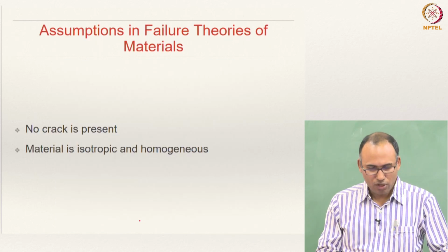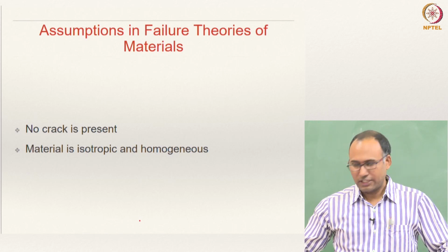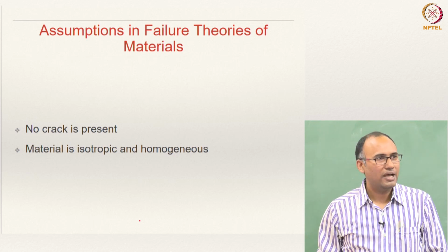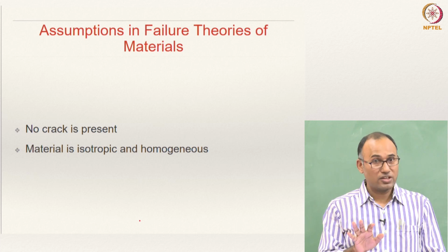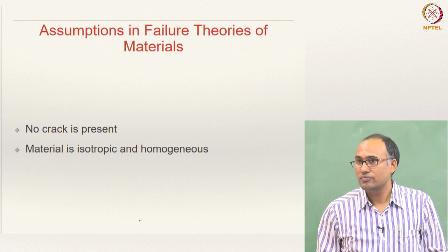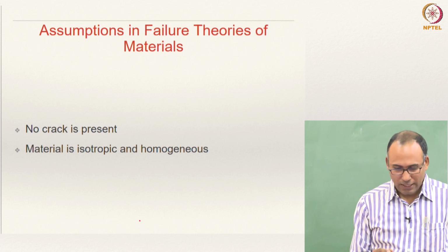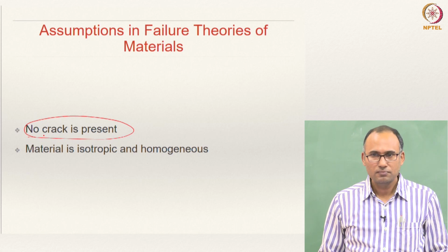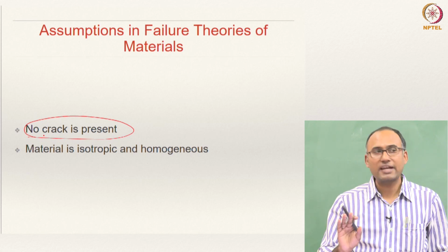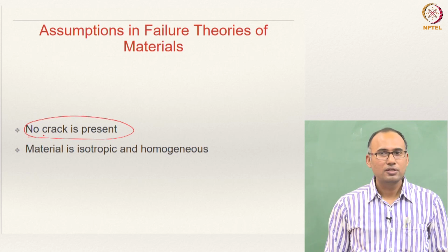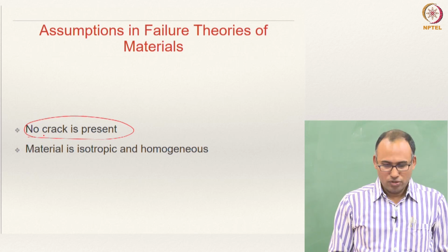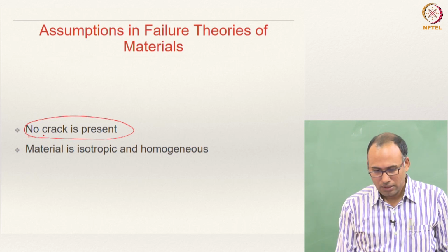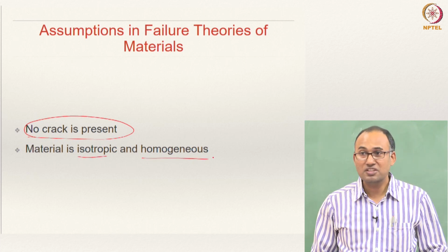Okay? All right. When we are defining failure theories, at least as far as this class is concerned, we have certain assumptions. The first assumption, as far as static failure theories are concerned, is that there are no cracks present in the material. It's a very important assumption. The moment there is a crack, you may have other issues. And in this class, we are assuming the material to be isotropic and homogeneous. This is also very important.